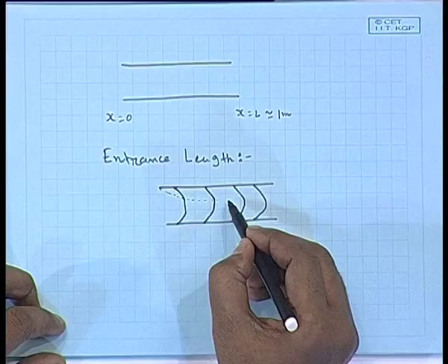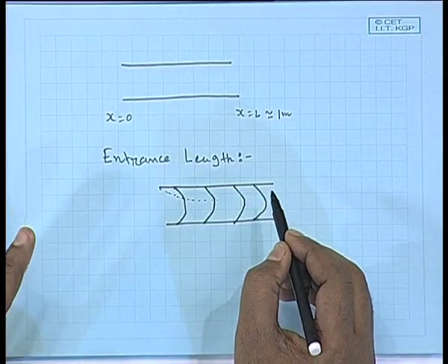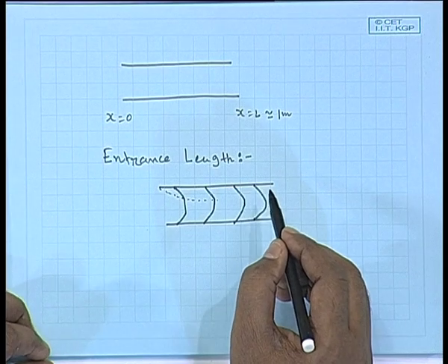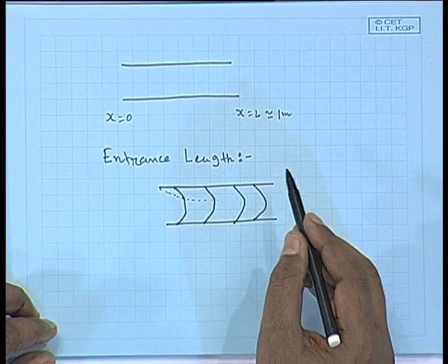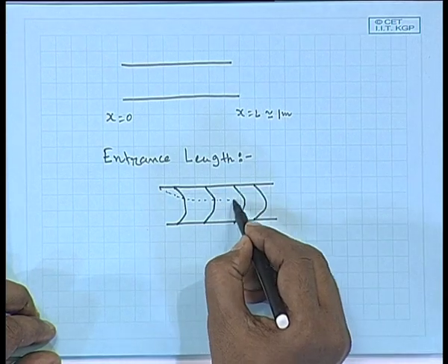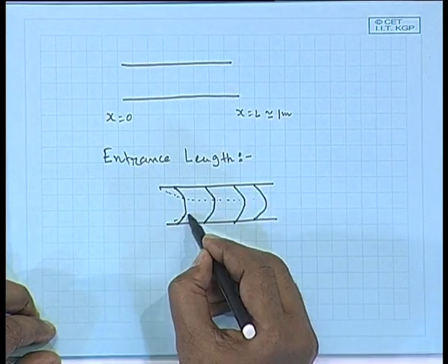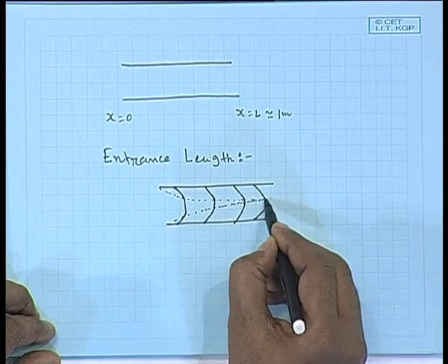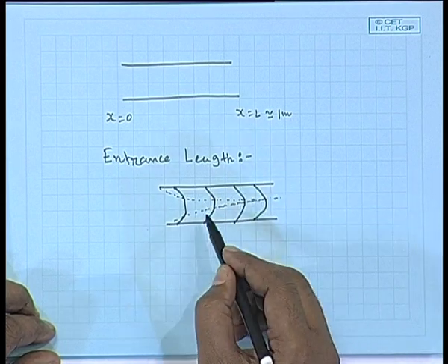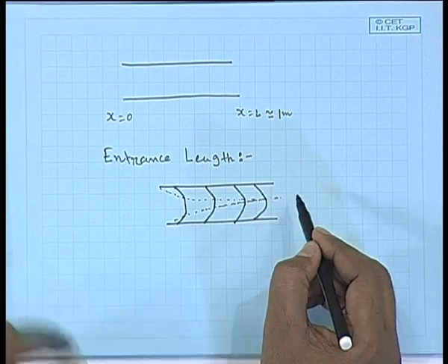Three boundary layers can coexist: concentration boundary layer, thermal boundary layer, and velocity or hydrodynamic boundary layer. Now, in this problem it is an isothermal case, so there is no temperature variation and no question of a thermal boundary layer. The velocity boundary layer is developing from both sides, and beyond a particular length both boundary layers will merge, and throughout the whole cross section you will get the boundary layer.